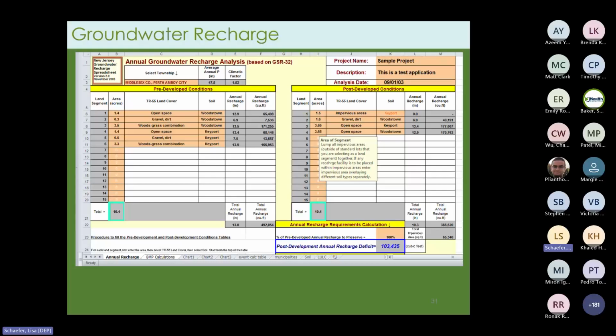Let's look at the inputs required. Infiltration is not the same as groundwater recharge. Infiltration is only the process to allow runoff into the subsoil. For groundwater recharge, the runoff needs not only to drain into the subsoil, it has to pass the root zone. The root zone is determined from the soil series selected.